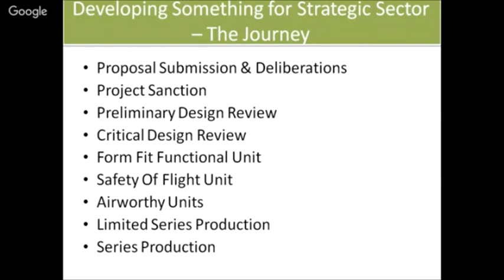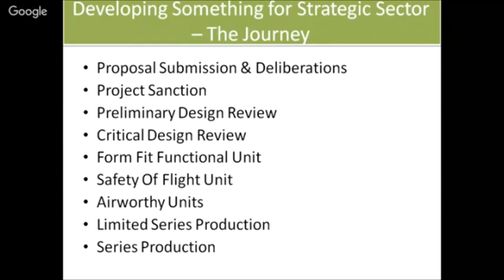And all those actors which I defined to you, barring the production agency probably. However, in our case, the production agency was always hand in hand with us. So all those actors, there is a PDR committee which reviews the design requirements, because what the agency gives us is certain performance requirements, certain environmental requirements, certain EMI/EMC requirements, plus an interface control document, a connector output through which we have to design the head-up display. So at the PDR level, basically the initial design is deliberated, and then once that is done, we go for a critical design review at a later stage.